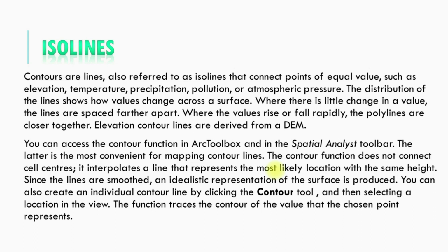You can also create an individual contour line by clicking the contour tool and then selecting a location in the view. The function traces the contour of the value that the chosen point represents.